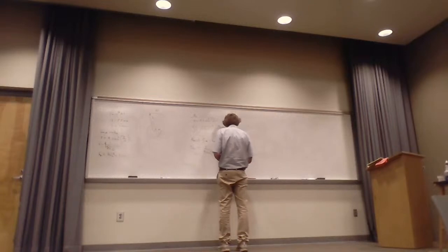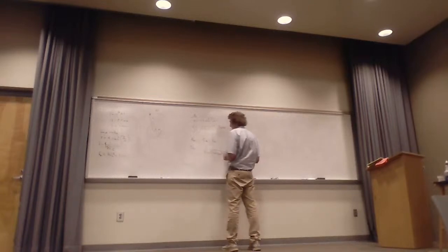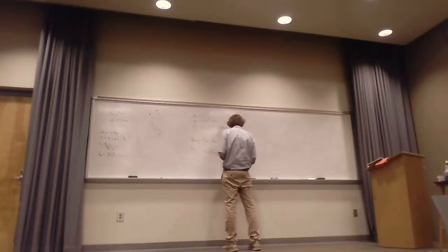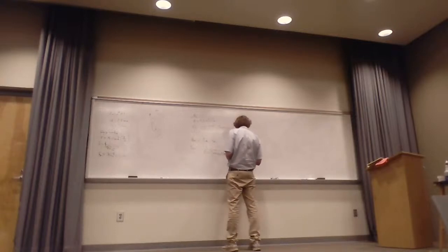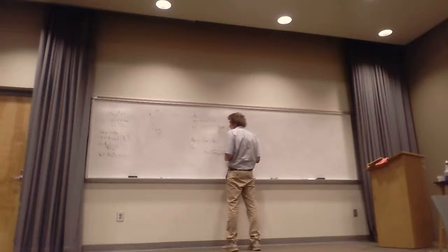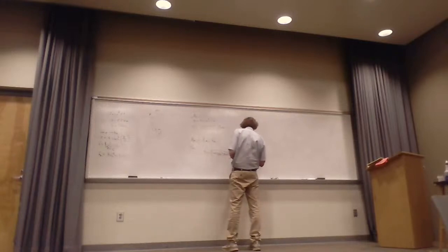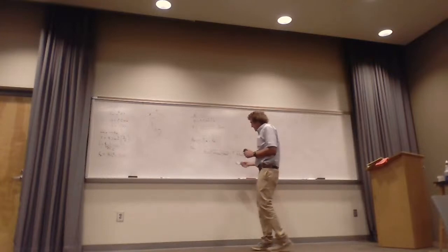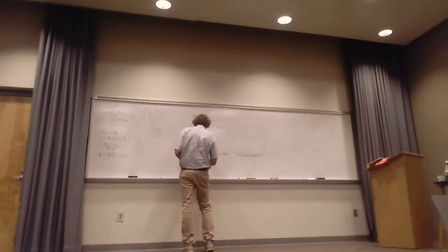Plus, then it's going to be 1 over conductivity for the aluminum, which is 3.5 times 10 to the 7th, times the area, which is 2 pi times the outer radius, which is 1 millimeter, 10 to the minus 3rd, and then times the skin depth, which is 9 times 10 to the minus 6. If you want to, you can give me the value for each of these separately.